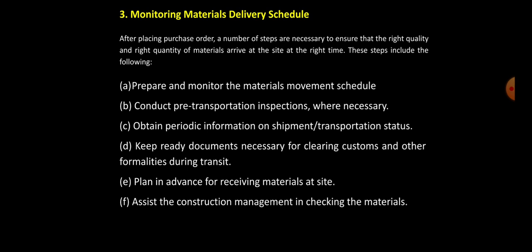Plan in advance for receiving materials at site. It should not happen that tomorrow we are having one particular activity and till today material is not available on site. So we have to plan it well in advance. Also we are supposed to finalize the unloading place so that there are no clashes on the site as far as placing of material is concerned.